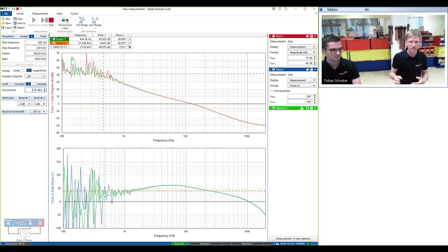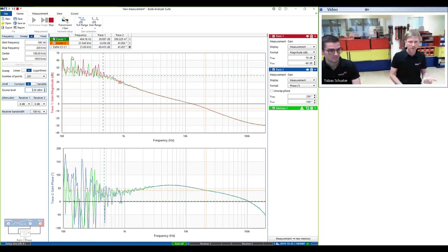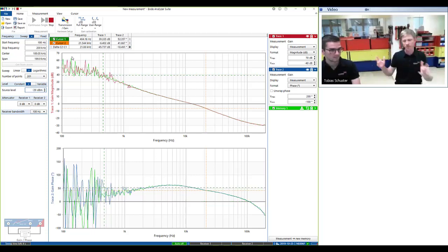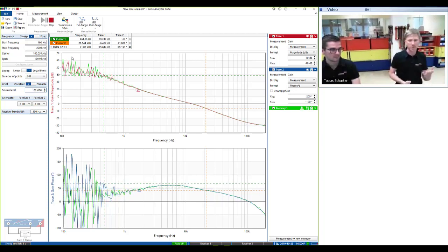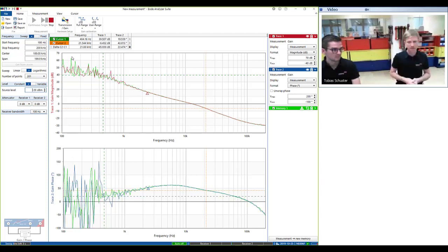So in this case, with around 60 dB, that's a factor of 1,000, only a fraction of the several millivolts that we inject will appear on the one side of the injection resistor, only some microvolts, and these microvolts are buried, or hundreds of microvolts are buried in the noise and the ripple from the switching regulator, and it's really difficult or nearly impossible to detect the phase in that case. So that's why we need higher injection signal at low frequencies.